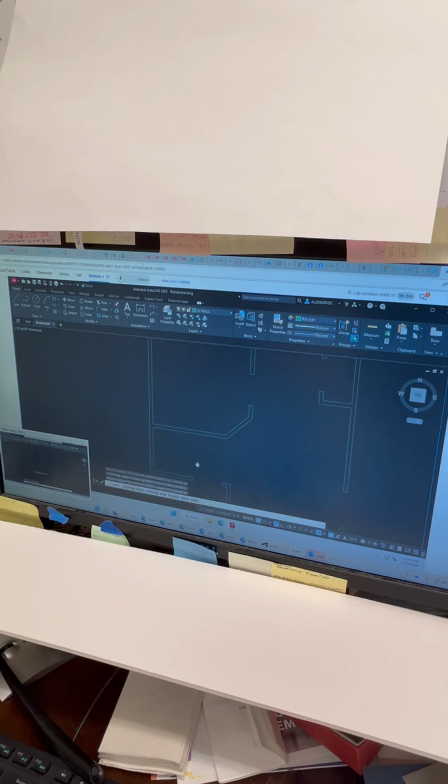I don't think you need to do any fillets. I think it's easier with the trim command. So some people think that maybe using the fillet in some situations, and it might be, but just kind of go around wherever the walls intersect. Go ahead and trim and see how it's satisfying, like they say on YouTube. They have satisfying videos. This is kind of satisfying.